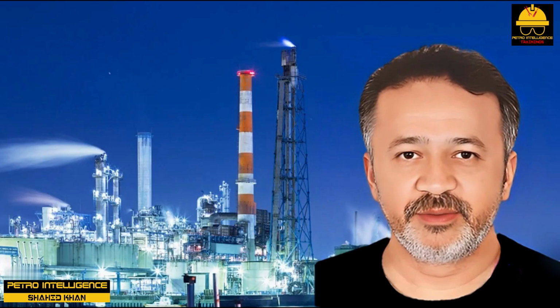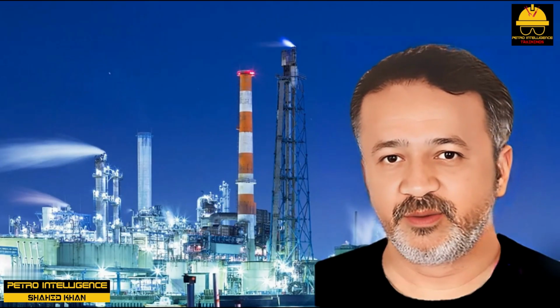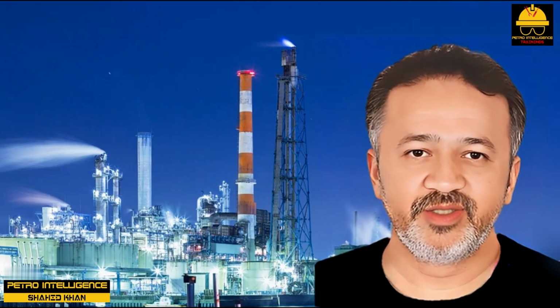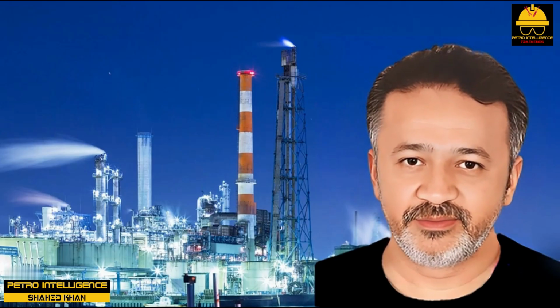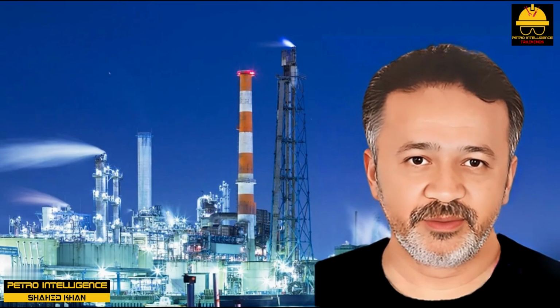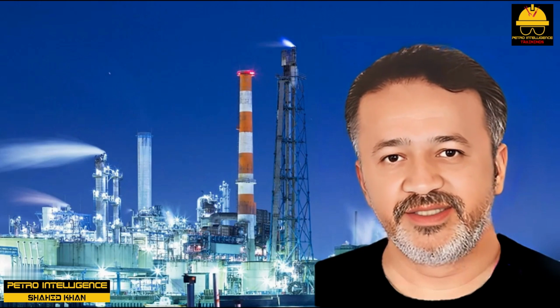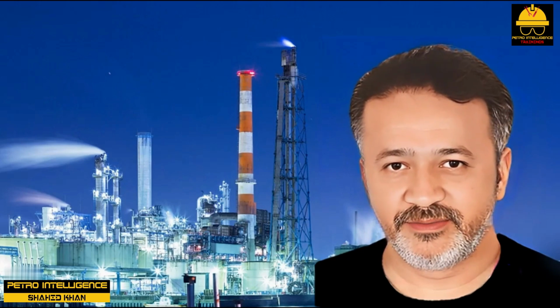Adjusting the refrigerant composition does not significantly affect the amount of horsepower needed to provide a fixed amount of cooling at a certain evaporator temperature. This statement is true even if the type of refrigerant used is changed completely. Propane, isobutane, freon, and ammonia all have roughly the same refrigeration efficiency.